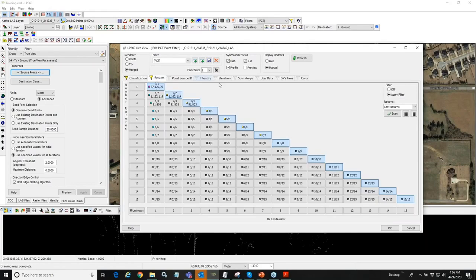But what I wanted to point out here is very standard with LIDAR. You want to take advantage of the fact that you have multiple returns with the LIDAR data. And the Quanergy M8 that we use on the 410 has 3 returns, which is quite unique for that class of LIDAR. Often they only come with just 1 return because they're designed for automotive and other applications where multiple returns aren't as useful. But the Quanergy has 3 returns, and we can use that as you would with any traditional airborne LIDAR to limit the points that we think are on the ground. If I've got 1 return and I have 2 other returns after it in the same pulse, then I'm pretty sure that first return is not on the ground. So I can filter that out of here.